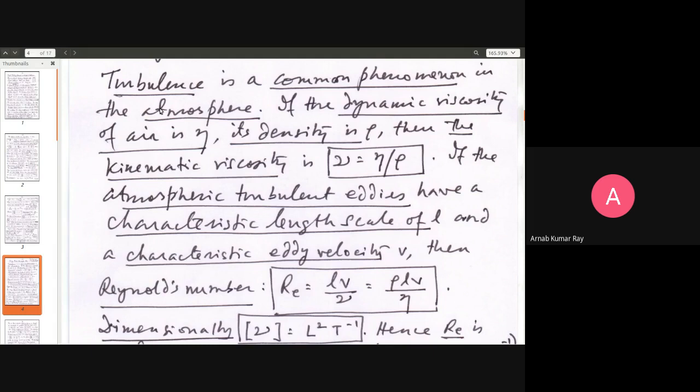Similarly, you also enhance diffusion in your coffee mug. You are in a hurry to go out. You can't wait for 2 hours for the sugar to dissolve of its own accord. So what you do is take a spoon and stir the coffee liquid. As a result, the sugar is dissolved that much faster. It will also help if the coffee is hot. Once again, you can see temperature enhances diffusion, and by disturbing the liquid, creating a lot of turbulence in the liquid, that is also enhancing the diffusion.